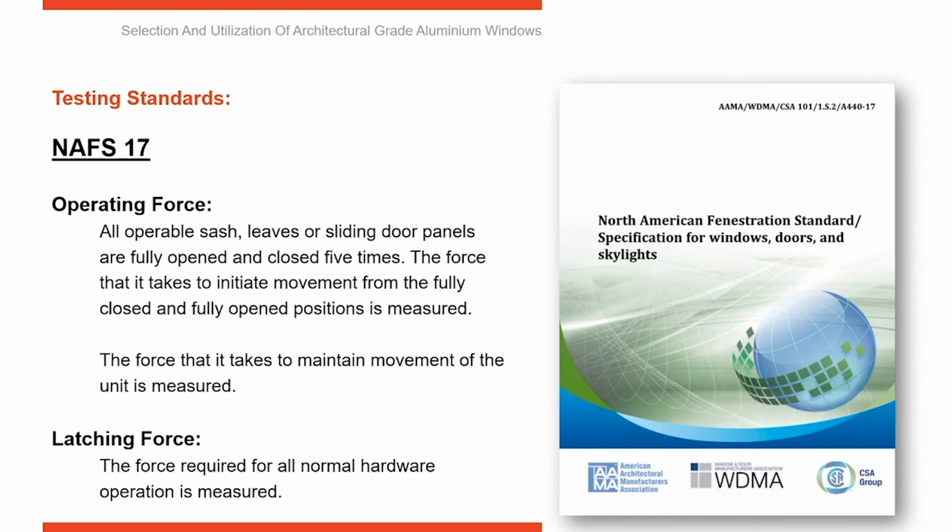Operating force codes such as ADA require that windows have a maximum operating force. So this is very important that all through this time, we're measuring the operating force of the window. How much force does it take to break the seal of the window, start it moving, and then pull it back closed and engage the frame and lock it again. So we're measuring the operating force of the window at each of those stages, breaking its seal, swinging open, then coming back and closing. Also the latching force, we're measuring the force applied there.